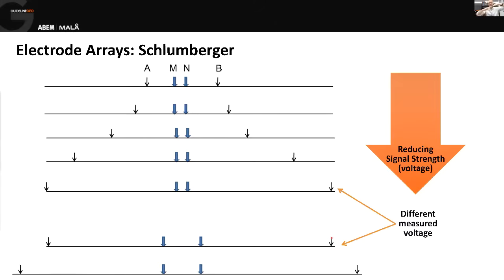We need to bring the second set of data, with the new position for the voltage electrodes, up to meet our original data set. And so we make sure that we repeat this reading. So you see the same current pair is repeated so that we can compare the difference between the 2 sets of data. And if we want to do it properly, we actually overlap by 2 or 3 readings. So we take a step back with our current injectors, take this measurement again, but with the new voltage pair. And that allows us to adjust to account for the fact that the signal steps up at the point where we change the spacing at the center.